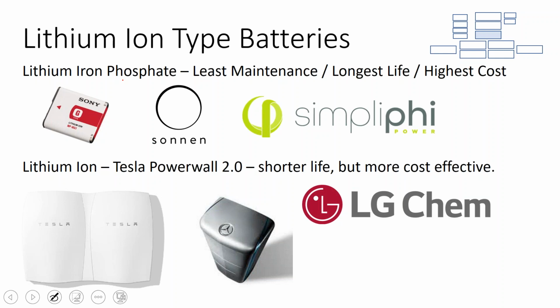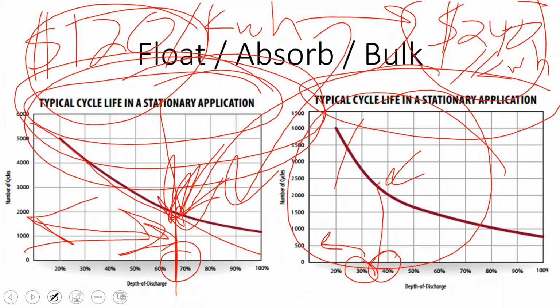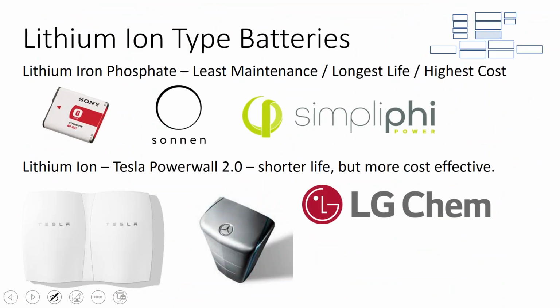So that talks about lead acid for a minute, and I group nickel iron in with lead acid, and these will all come back when we talk about our case study in more detail. Then we get into lithium ion batteries. I see lead acid finding a niche in the off-grid market where you just need the raw capacity, and lithium ion batteries are just too expensive right now. In the off-grid market, generally you have a more rugged individual who's willing to do some battery maintenance.